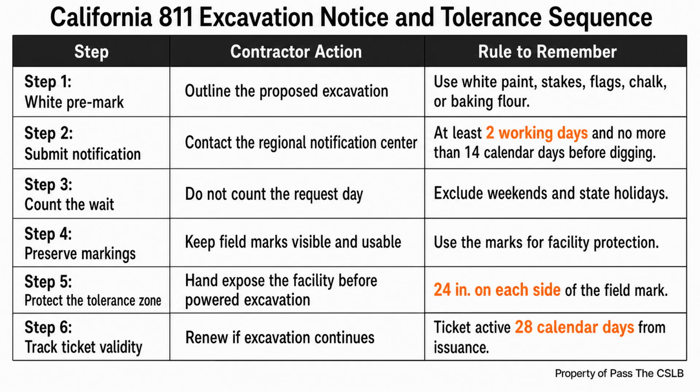Once legal and utility control is protected, the contractor still has to transfer the building layout into a form that can survive excavation. That is where batter boards and string lines become useful. Survey points may sit close to the exact area where footings and trenches will be excavated. If the crew relies only on stakes inside the footprint, the first grading pass can destroy the layout. Batter boards are placed outside the excavation area so the working lines can be removed and restored while the ground inside the footprint is disturbed.